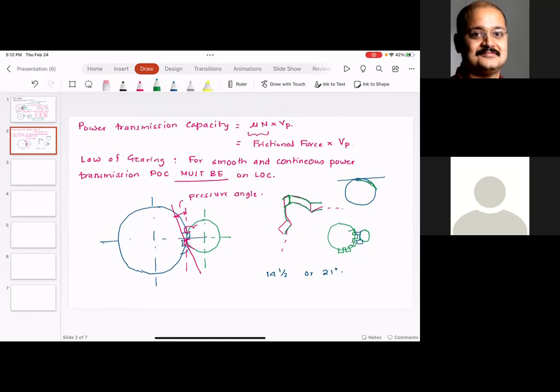So in other words, what you can do is roll this line back and forth onto this circle, and the point that is traced by that line is nothing but the involute. So the gear can be cut with the involute profile, because the involute profile would allow proper engagement and disengagement of teeth. Please note, here is something super important.